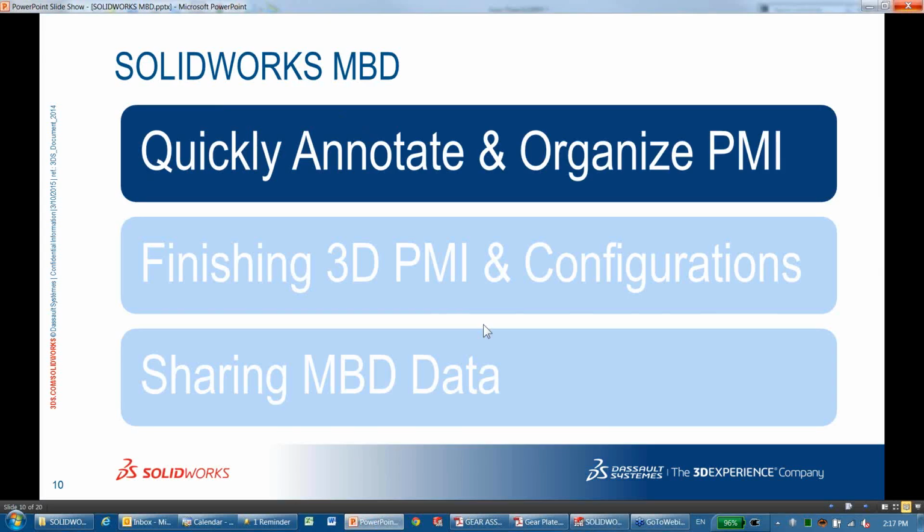So really, the idea behind SolidWorks MBD is to be able to really quickly annotate and also organize your PMI information. Really, it's not much different than making a drawing, except that you do that in the 3D model. You create your views, you organize your dimensions and tolerances in those views, but you do that in the 3D model instead of creating a new file, having to manage another file, which is the drawing. You just keep everything in your 3D model.